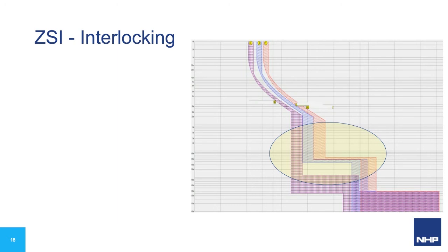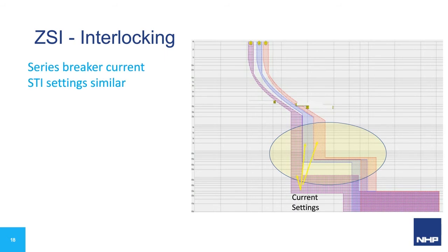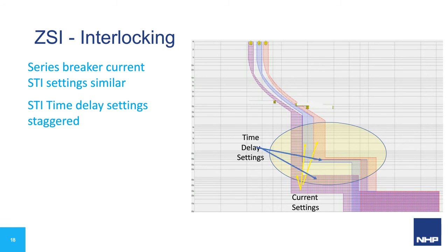The STI settings are generally based on a multiple of IN, or nominal current range, say between 2 times IN and 14 times IN as a low-level short circuit current pickup value. Each of the breakers has a time lag level threshold. Each breaker's countdown clock is armed upon crossing of the short-time short circuit current level threshold.